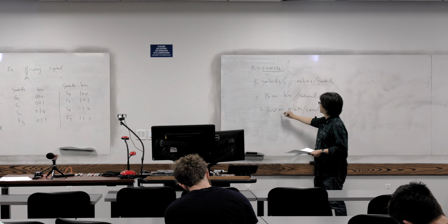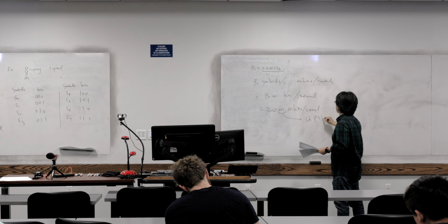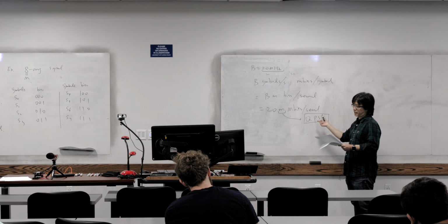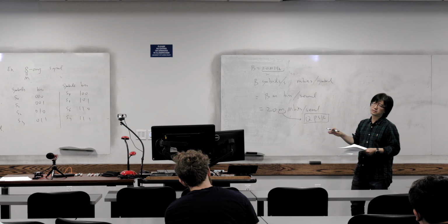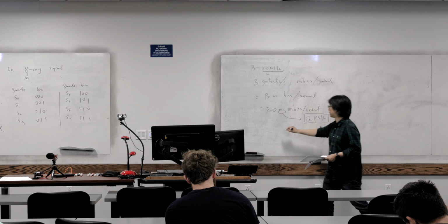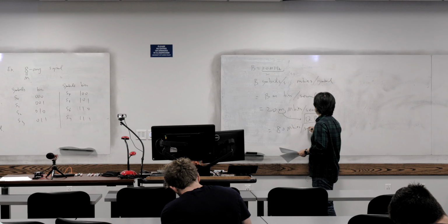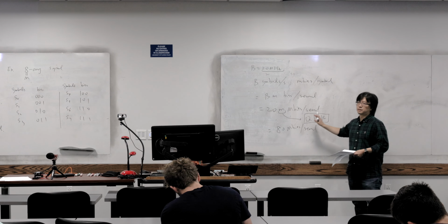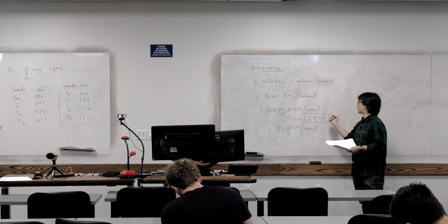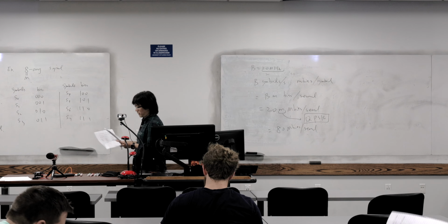Let's say we use QPSK. We didn't learn that before, but let's assume QPSK means that we have 4 symbols instead of 8. If you have 4 symbols, then this formula will give you 80 megabits per second. That's how we compute how many bits per second we can transmit. That'll be it for today. We're going to cover QPSK later, so don't worry about it if you don't understand that. Okay, great. Thank you.